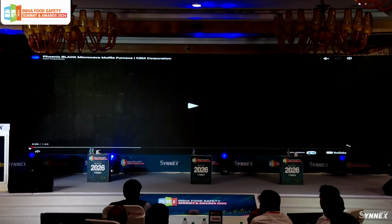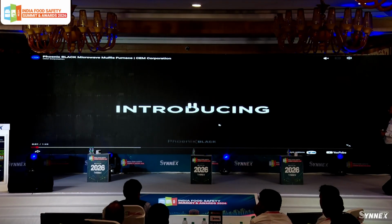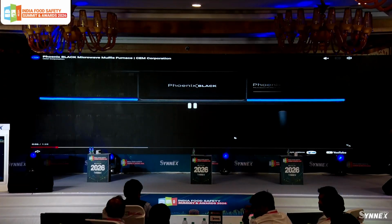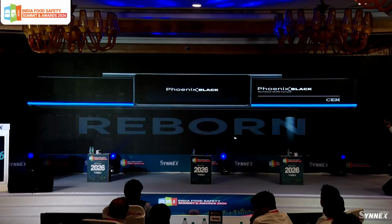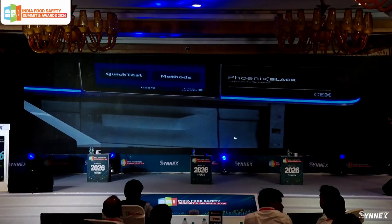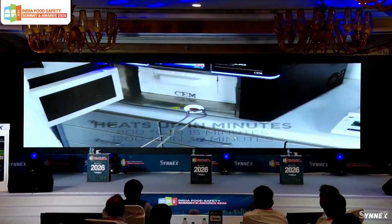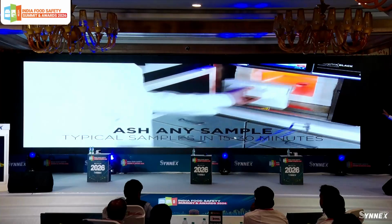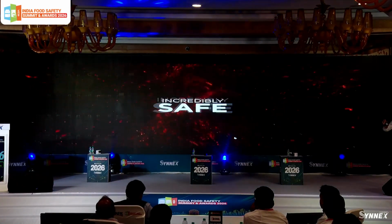Yeah. So this is the ashing system. If you see, this is with an integrated PC. So all the data will be stored. You can transfer the data to LIMS connectivity also, or any server. Basically, it is as per the AOAC. It's silicon carbide. You see, this person has kept the crucible. The temperature now is 853. It can reach 1000 degrees Celsius within 15 minutes.